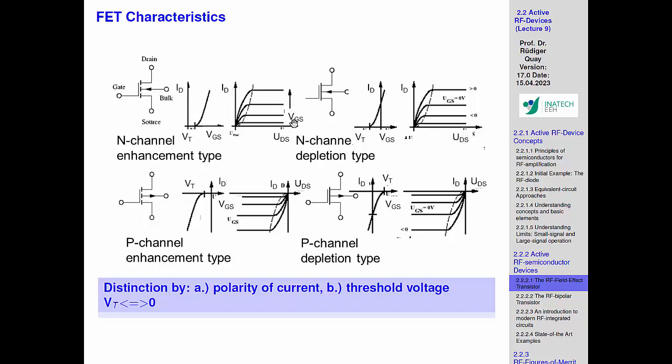So, for example, the normal MOSFET we are using for N-type, the one which we just talked about, typically has a positive threshold voltage. So you bias it at plus something and you get voltage and current. But it's not always the case. Many RF devices also have a negative threshold, although the current is positive.